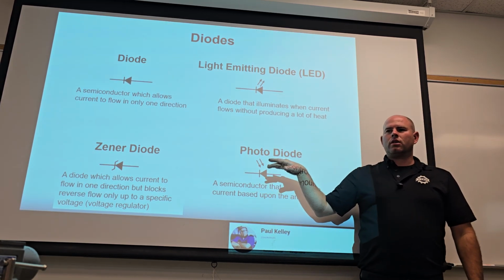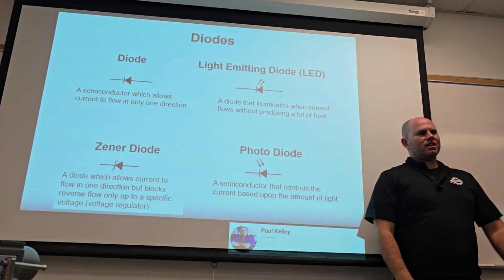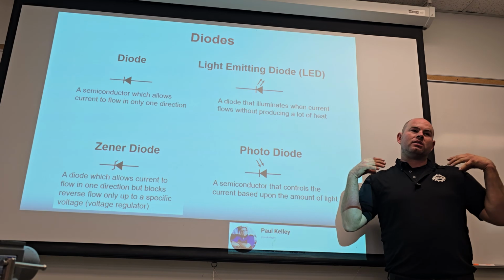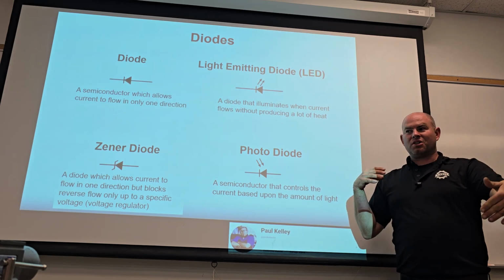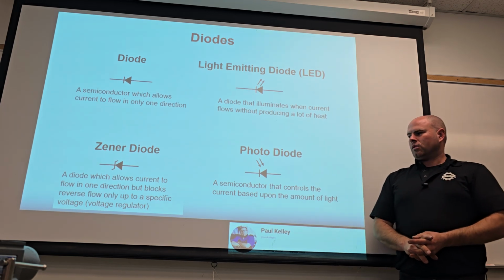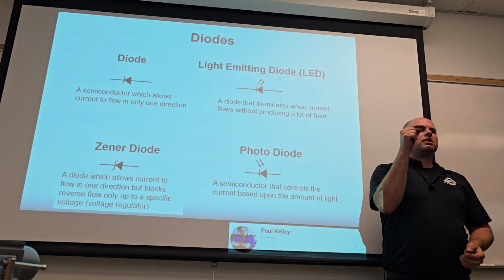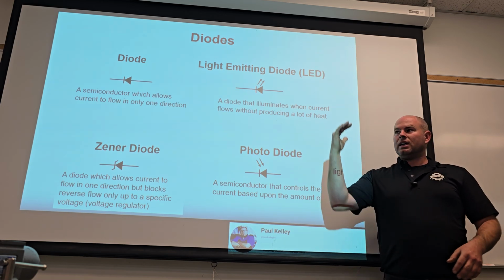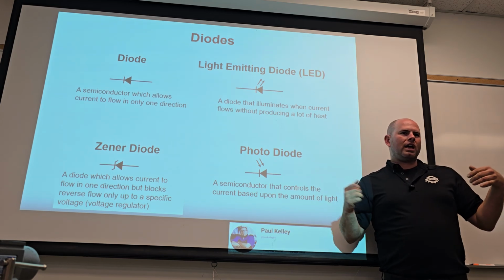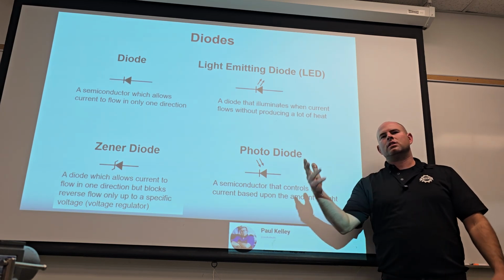We also use these for the automatic air conditioning system. You guys know how it is here. California is kind of crazy. Even if it's not that warm out, if it's really sunny, the sun feels hot. But as soon as the sun goes down, it feels cold. If you have automatic air conditioning, like auto HVAC in the car, the fact that it's sunny or shady makes a really big difference. If you set it to 68 degrees and it's sunny outside, it knows it's sunny, so it'll run some AC. But if it's 68 degrees and dark outside, it'll kill the AC. If you don't have this, it'll be constantly too cold when it's dark and constantly too warm when it's light.